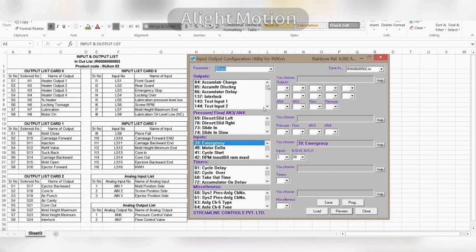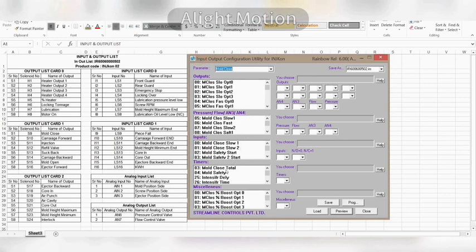Now our fourth step is timer. If you did not enable the timer in the program, and you want to run any function in the PLC on the timer, it won't run on time; it has to be enabled in the program. As an example, in the parameter, in mold close, going into timer, click on mold close total time. In the timer, 00 is disable, 01 is enable, 02 is permanent on; these 3 options will appear.